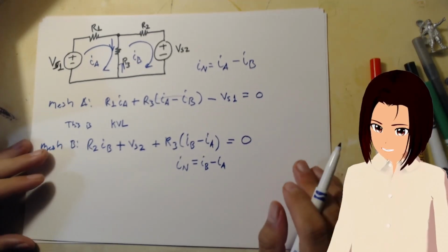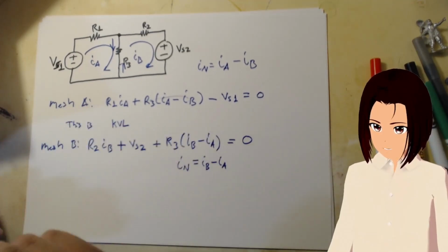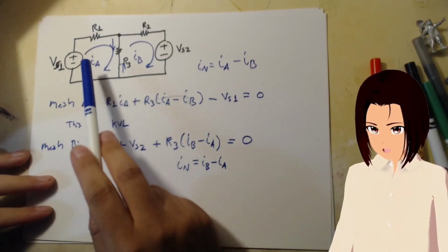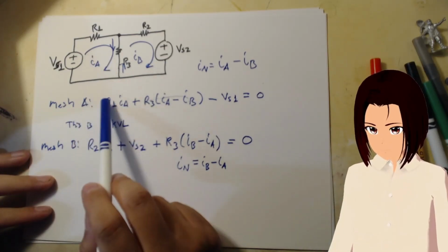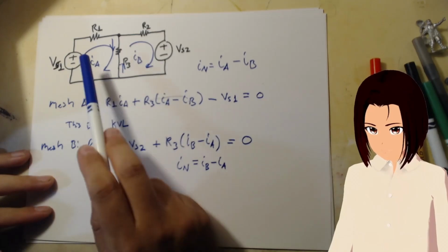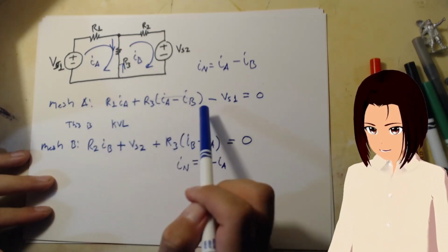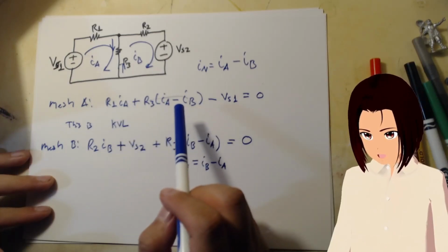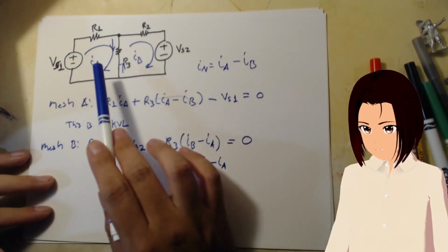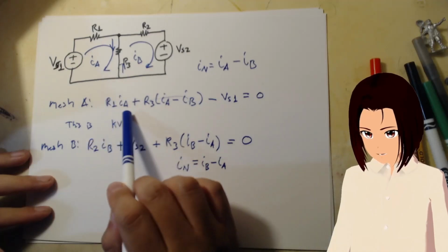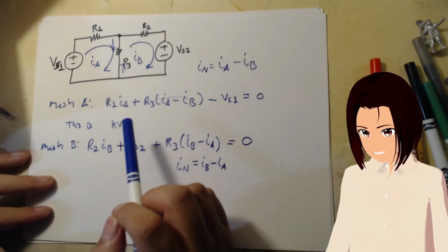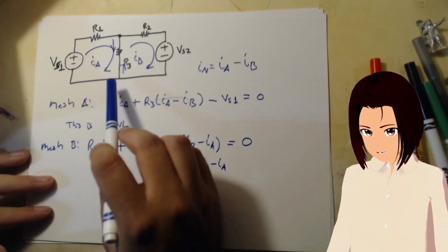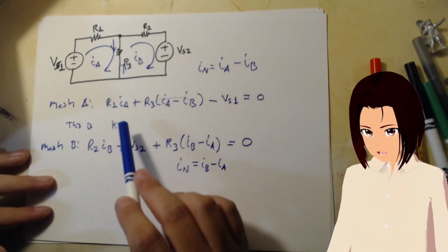One thing I want to say is this. We have our equations and we got them by looking at the mesh equation. This is the mesh current, and we have that voltage here because this is fundamentally KVL, but we're expressing KVL in terms of the mesh current, which is IA. That's all that we're doing. It's simple, it's just algebra. Same thing for mesh B. We're imagining this is the mesh current, and we're expressing it all in terms of B.